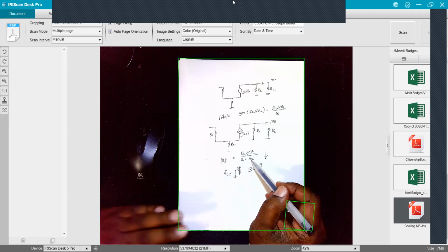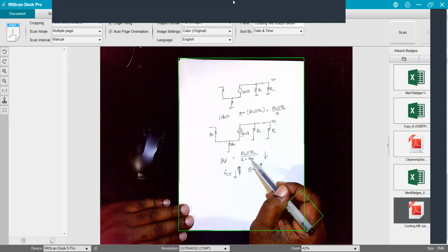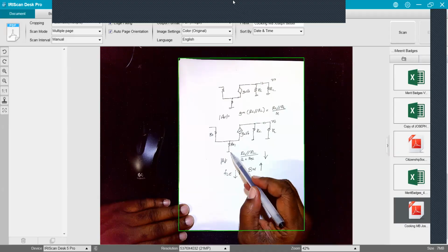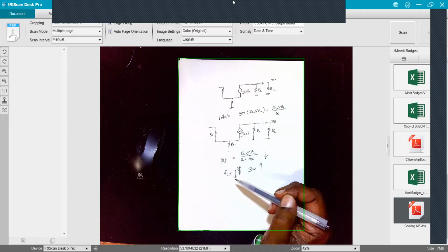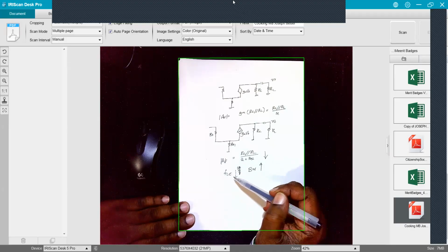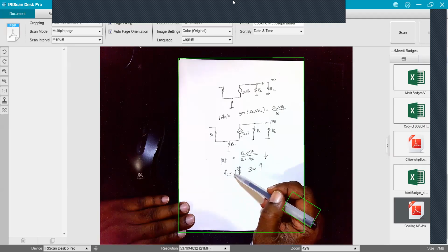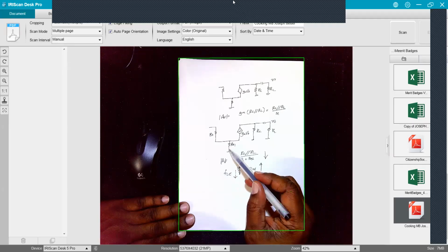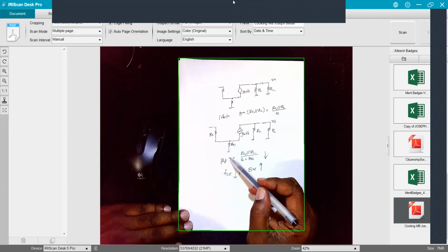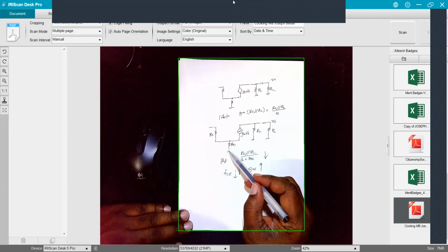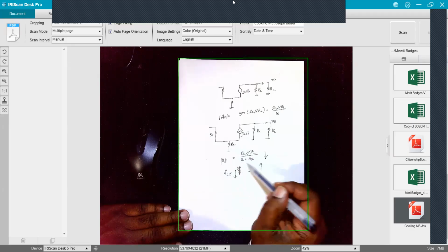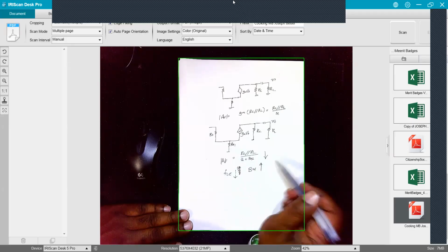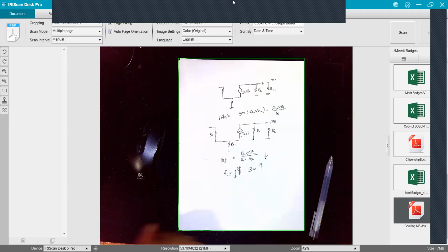So if I had more gain than I wanted, rather than changing out the entire value of that resistor, say instead of going from 1K to 1,024 ohms, I would just take the 1K and split 24 ohms off from it, only bypass part of it, and then that would decrease my gain if I'm getting too much gain, resulting in distortion at my output.